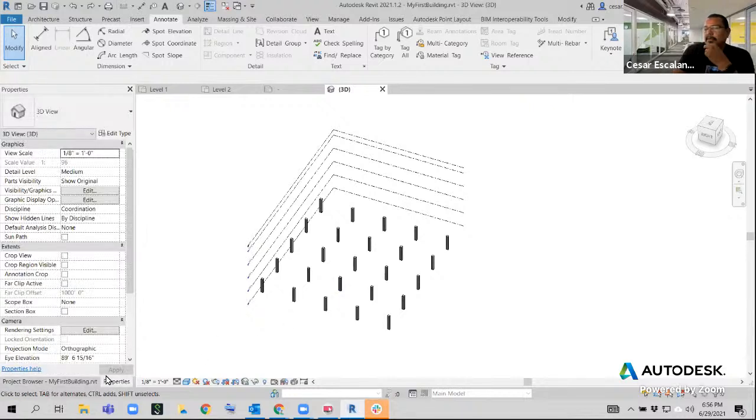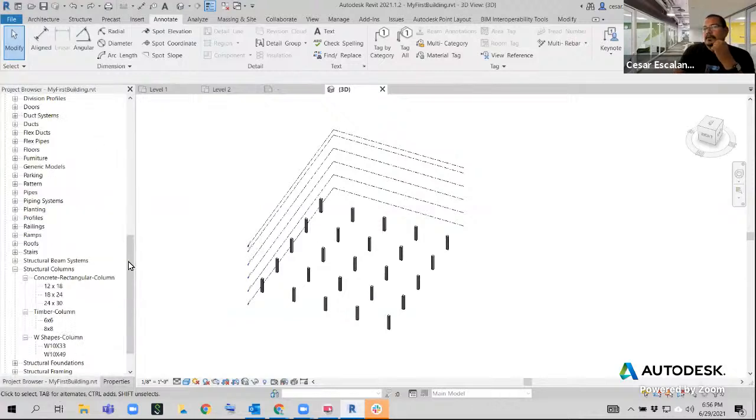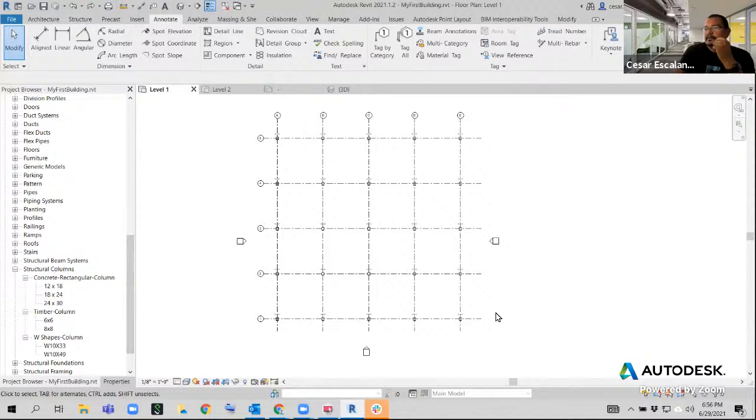All right, let's build very quickly a floor, a slab. So this level is the parking level, the underground parking. And I'm going to move my view to level 1. And I'm going to create a slab on grade that is 6 inches in thickness and that is 2 foot away from the grid intersections.